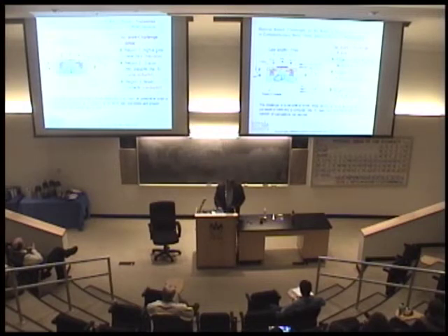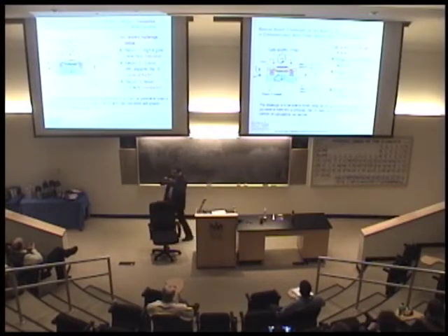So basically you're creating this channel between them by playing with the gate voltage. If you change the gate voltage, you can make this state into the off state, which blocks, there's no current, and then you can play with the gate voltage again. You can have a current from source to drain, which is the on state. So that's a typical switch, on an atomic scale, of course.